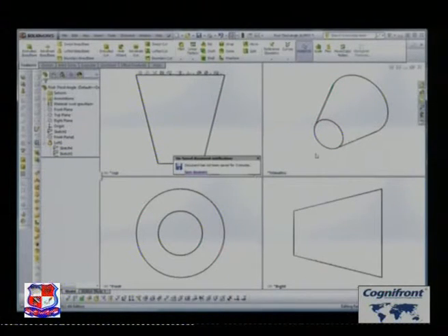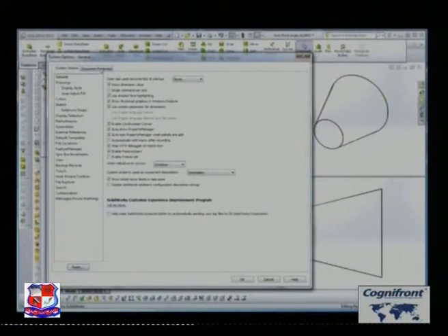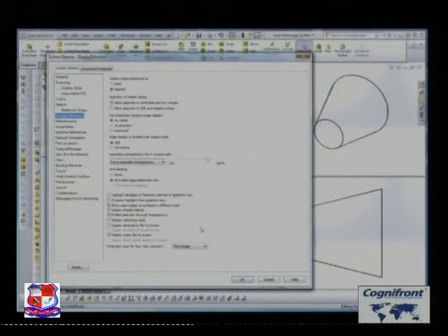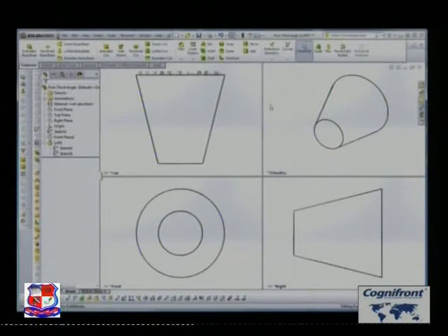This is folded down, and then we have our trimetric, bimetric, or isometric up in that corner. What makes this different in the first angle projection is that it's just a little bit turned around. Easy to follow, but just a little bit different. So let's go to our options. Go to your system options down here, go to display selection, and down here it gives you the opportunity to change between first and third angle. We're going to change that back to first angle, go to OK.